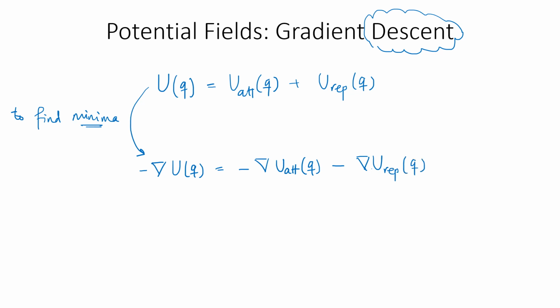Now with this realization, when I'm going to do that, I will have in the configuration space the torque experienced by the manipulator, and these torques are going to be observed by the joints. Since you know that these Q's are the same Q's that we defined during the Denavit-Hartenberg convention, these are going to be Q1, Q2, all the way to Qn for the N-link manipulator.